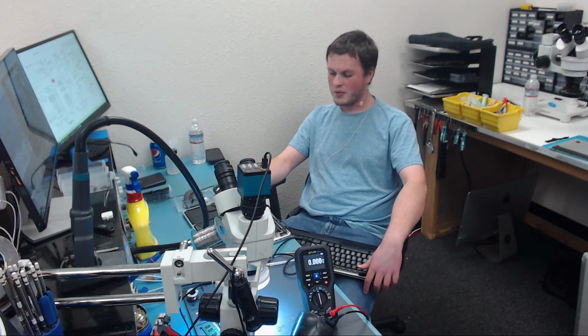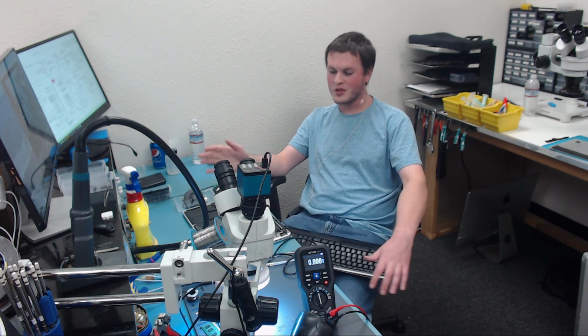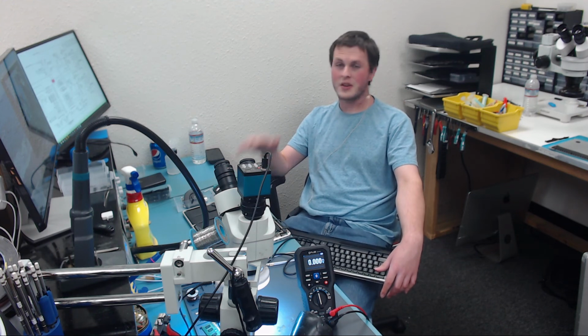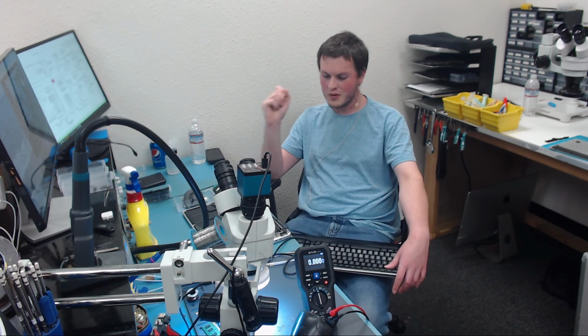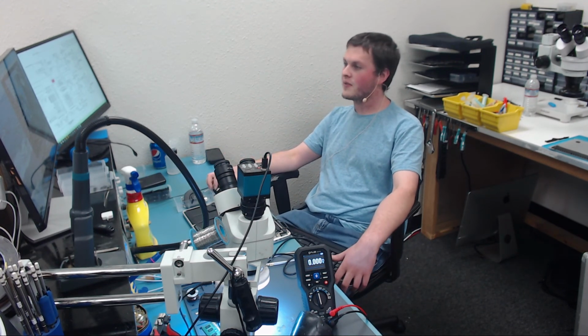I've had people that have had some place replace their GPU with a piece of junk one, and same thing. It'll work for a day, and then it starts doing the black screen thing because it's the joints on U8900. So, please, I'm going to make this video very clear on my channel that this is what causes it. It is not the GPU. It is almost never the GPU. It is just U8900.